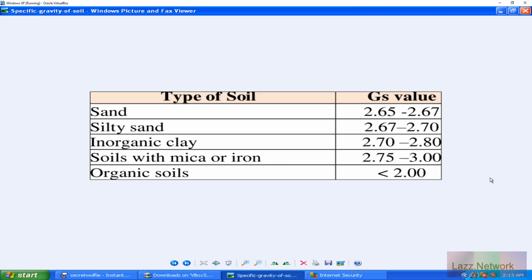Now, for specific gravities in general, it's usually determining the value with water, which is what we do as well when it comes to soil material. The only technical thing we have to do on our end when it comes to soils is that it has to be deionized or distilled water, so water that has no minerals or particulates in it that could affect the density, because those minerals and particulates will add density to the water itself.